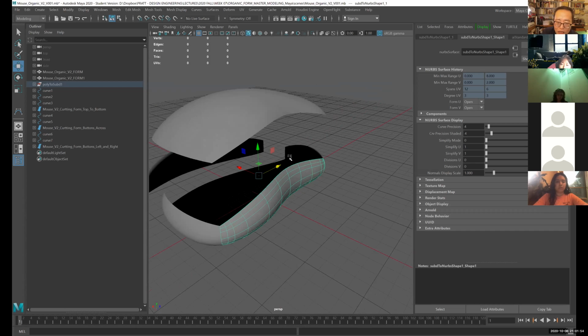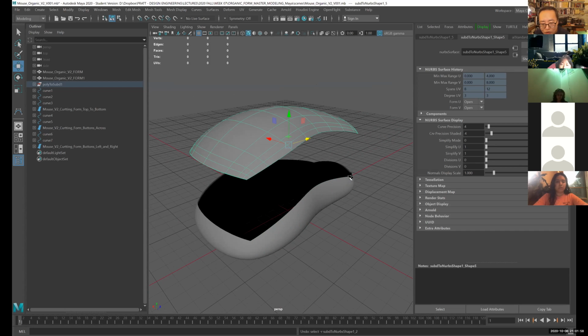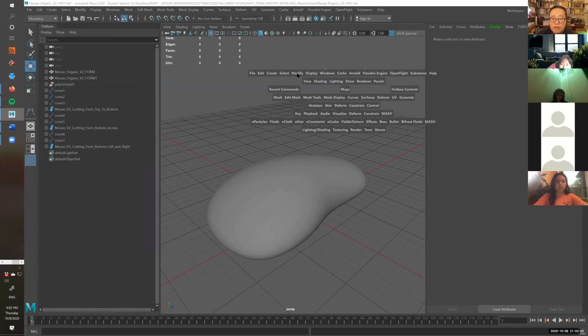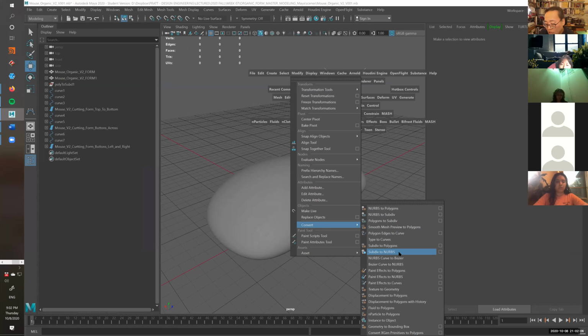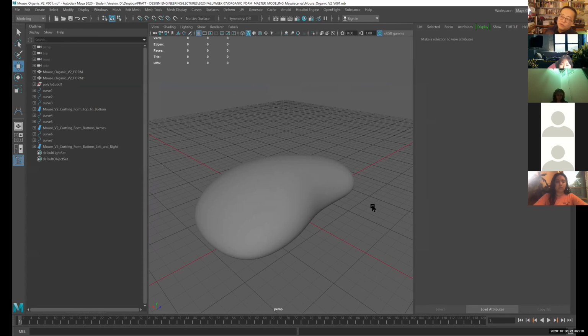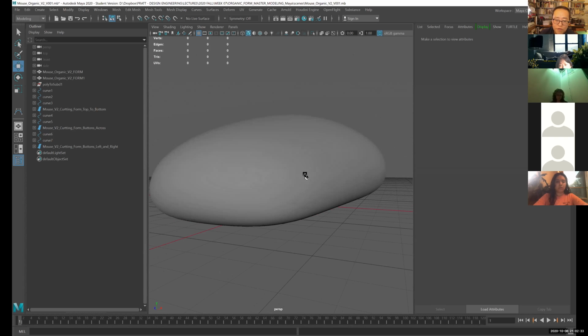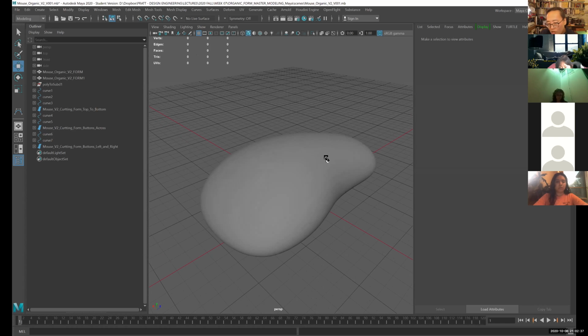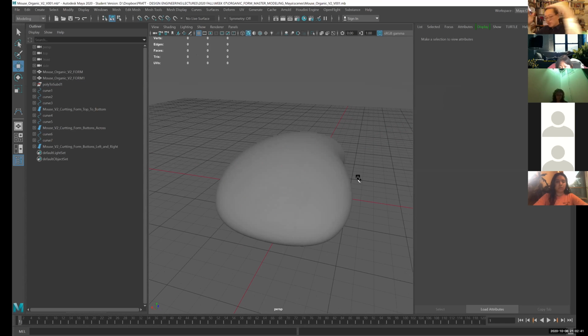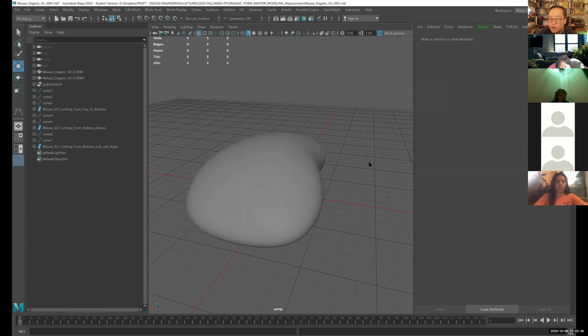I'm just illustrating that by making the conversion, using this command that does the conversion from subdivision to Nurbs, it does all this hard work that you would have had to do manually. It did an automatic calculation of going through the entire form, analyzing the flow, analyzing the whole topology, and saying I could split up this form into a four-sided quad here, here, and here, and here's the end result. A combination of four-sided patches that are curvature perfect. There are instances where the curvature is not perfect in extreme cases, but for the most part it will come out good. So you don't have to worry about curvature continuity between boundary surface, network surface, none of that. You're at concept stage, so you're not there yet. You shouldn't need to worry about that, okay?